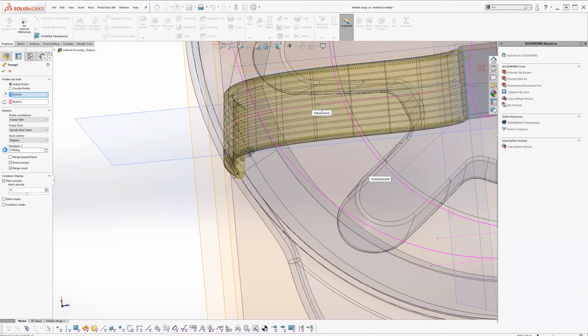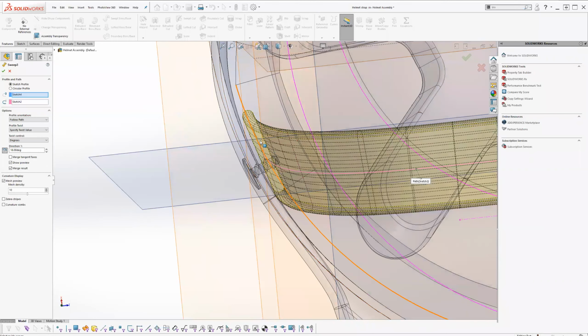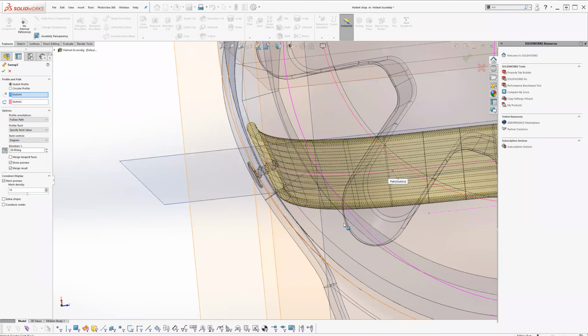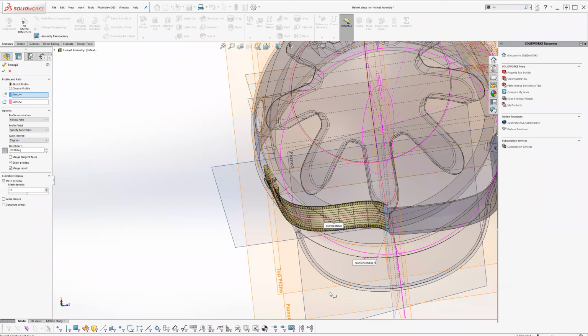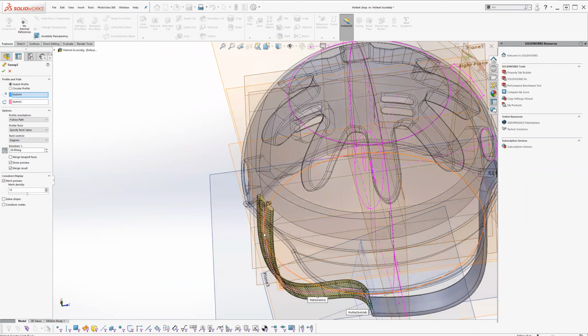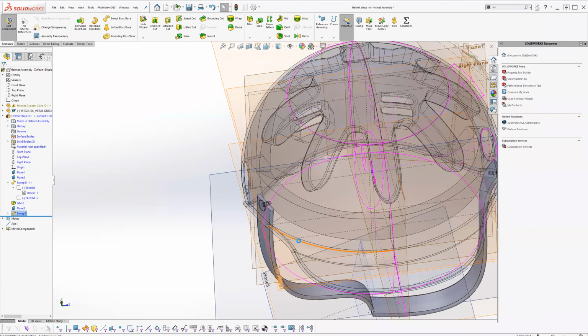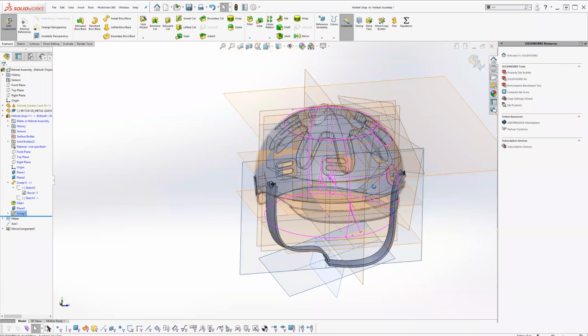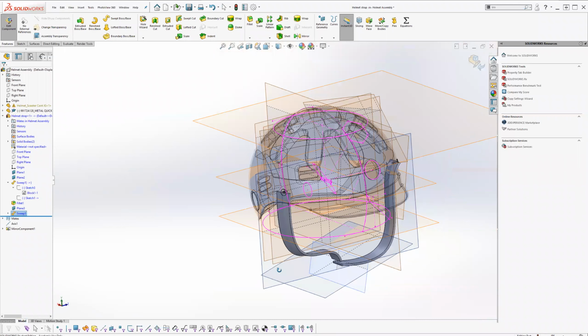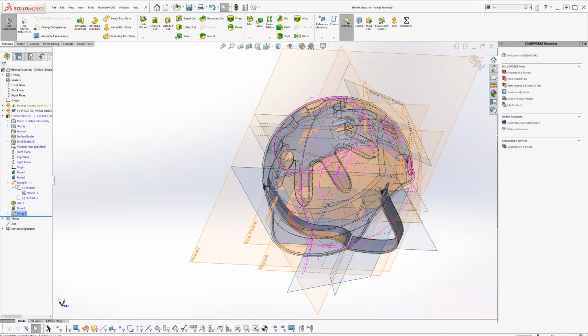Here, I'm going to change the direction of the twist at about, let's say 18 degrees or so, so that it ends pretty close to... actually I'm going to maybe go back up a little bit, maybe 20 degrees. So as it's traveling along its path, it's also twisting at the same time. That'll add a little bit more authenticity, I guess, to the way the strap is supposed to get swept.